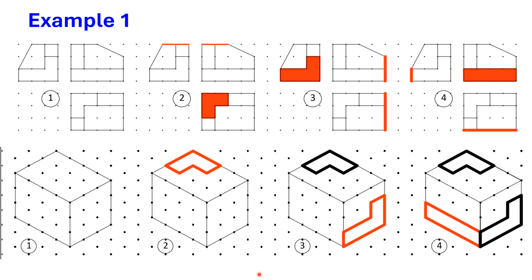If you see the front view, it is appearing like this, and if you see the top view, it is appearing with the 30 mm and over here. So it is also coinciding. So you will be drawing this plane, this surface in this view, in the box. Now you go to the next surface.